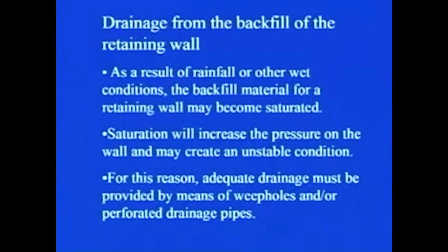See, I was telling you that in the analysis of the retaining wall, we are not considering any pore water pressure which is getting generated, maybe due to the presence of a groundwater table or any other source of water. Usually in the analysis we do not take into account all these things. However, proper design of the drainage is done in the case of a retaining wall, so that there is no development of any kind of pore water pressure.